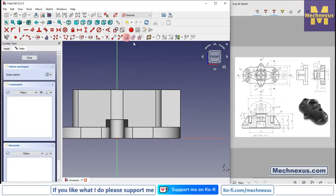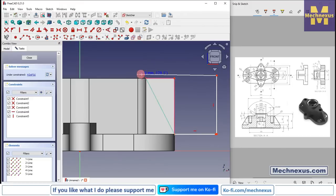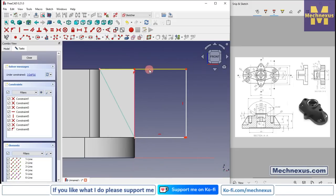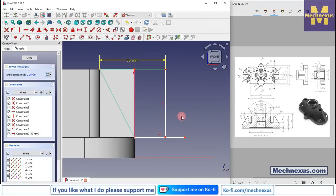Here click on the project and we will project it, and here we will select a line tool, create a line horizontal, then vertical, and close this profile, select this line and point and add a coincidence relation, and here we will select this line and add a rough dimension of 50 and use the trim tool to trim it.